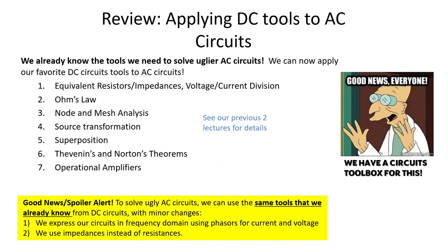So let's just do a quick review before we move on to frequency response. In our past few videos, we have learned how we can apply our favorite DC tools to AC circuits. And so we can now take all the tools that we learned from our DC circuits, like Ohm's law, voltage and current division, superposition, all these tools, and to solve an AC circuit, all we need to do is express our circuit in frequency domain, and then solve for unknowns using impedances instead of resistances.